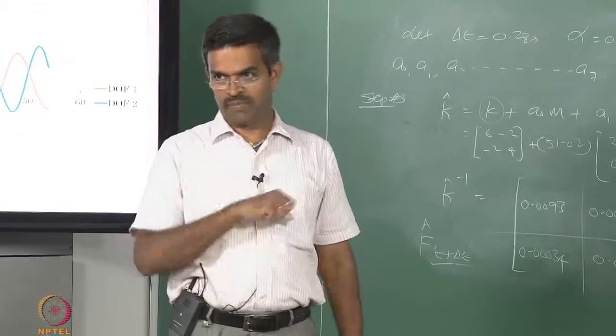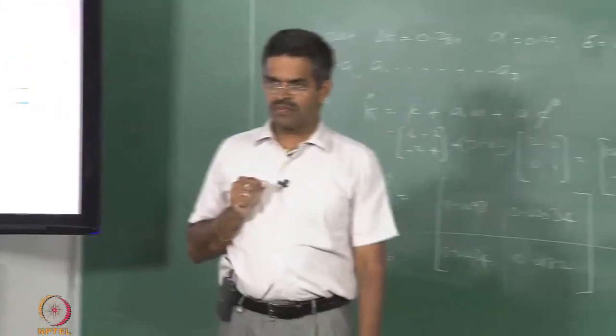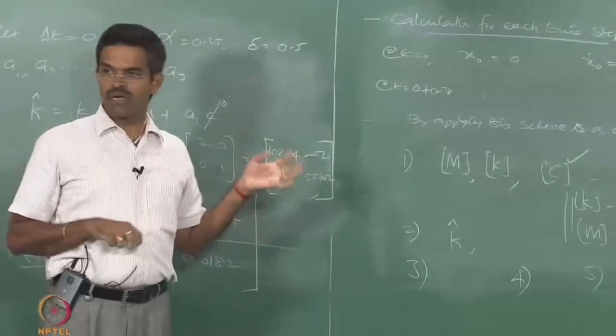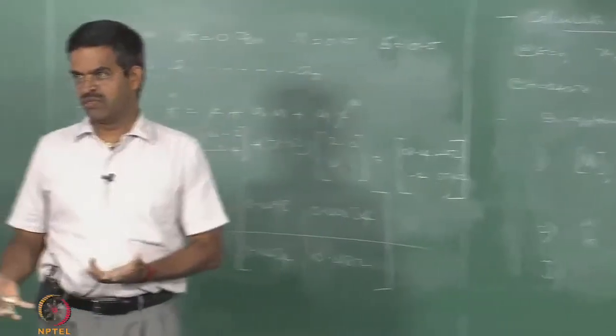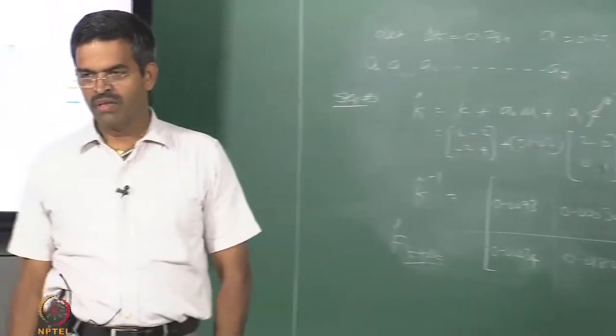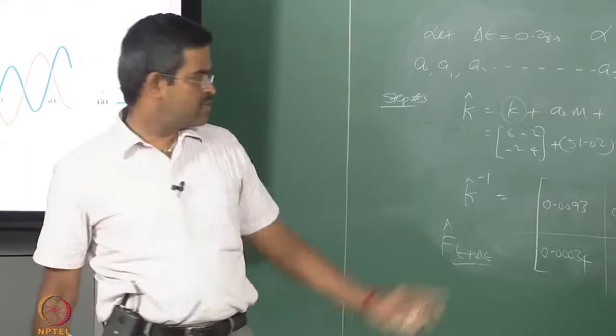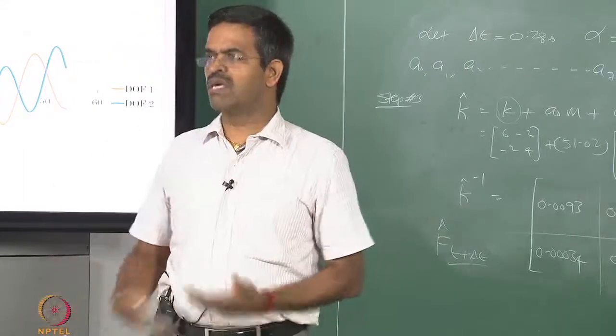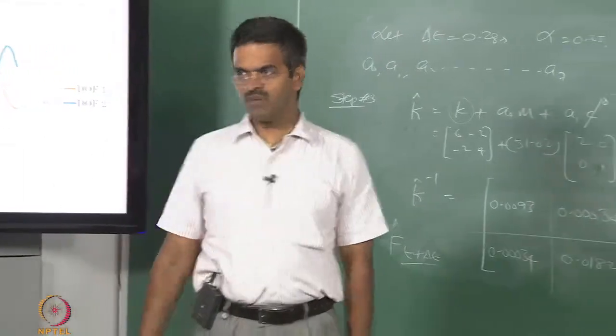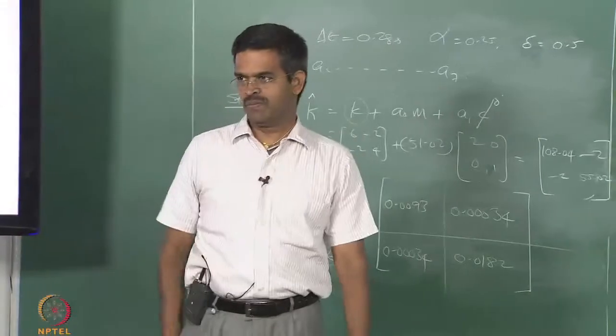One can ask me a question, why displacement? Okay. Compliant systems are displacement bound, they are not acceleration bound. The systems are actually meant for large displacements, that is why they are called compliant. Okay, so we compare with the displacements and check.